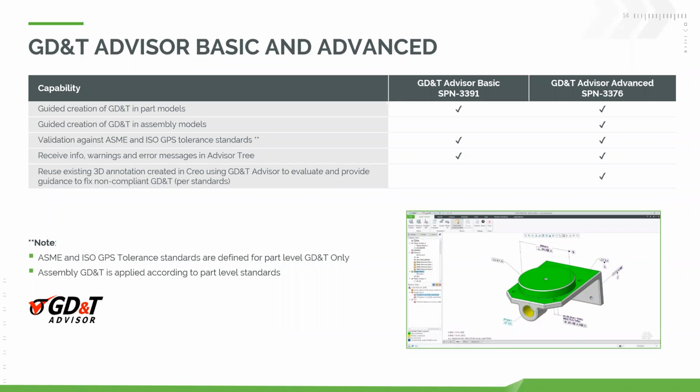Okay, I think this is the last one. If you change the dimension tolerance in a Creo drawing, my assumption is it transfers back to the 3D model. Thus, any annotations in the 3D model can be shown when detailing a part. Yeah, that is essentially how it works. What you're doing with those annotations in 3D is showing what's defining the feature, so if you change a tolerance that defines that feature, it would be retroactively shown in a 3D annotation.